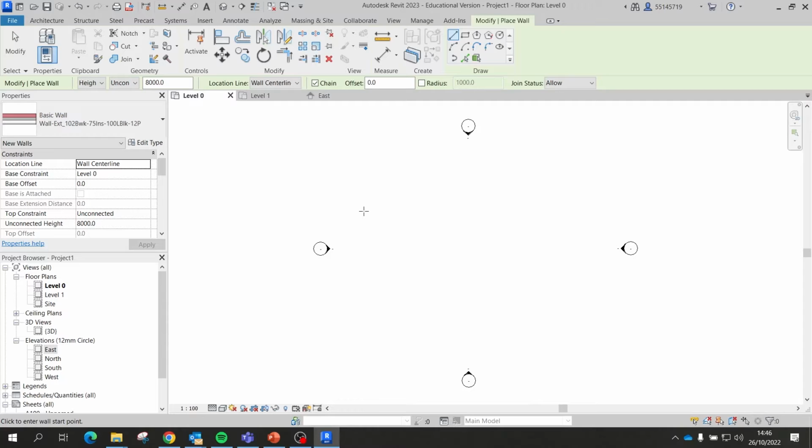Remember what I told you. I'm drawing probably a rectangle, or what I expect to be on a flat plan, a wall, right? But that will have an effect on what? 3D views, section views if I have, and so on and so forth. So for this reason, when I'm drawing it, Revit asks me a few information. It will ask me, wait, but how tall should it be? I need to know now as you're drawing it. So you see that up here in this green bar, I'm getting a series of information that I can input for Revit to complete the action properly.